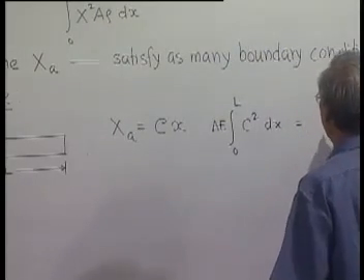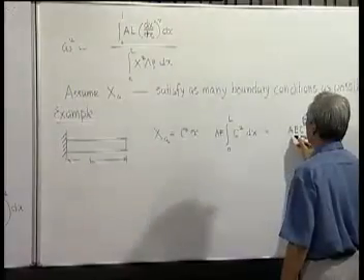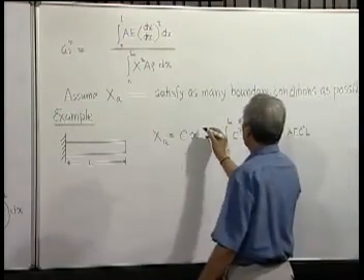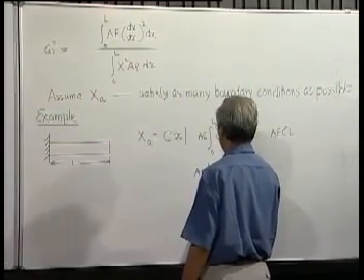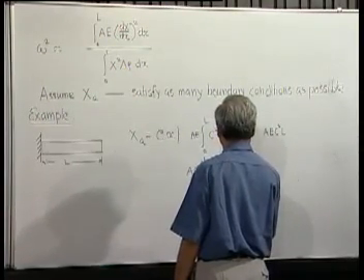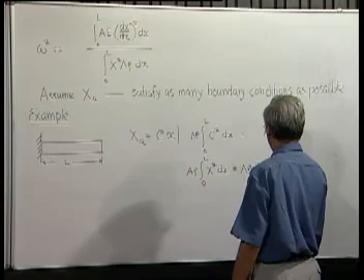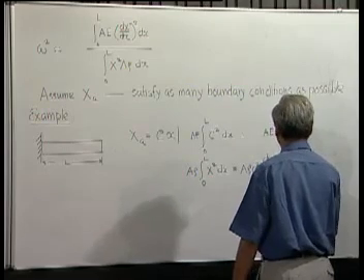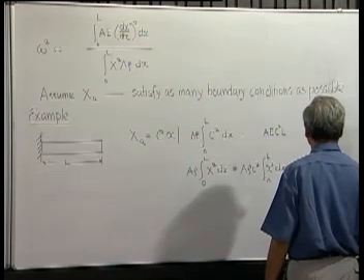So the numerator becomes A E c square L. For the denominator, again A and rho both are uniform as a special case, so this is equal to A rho c square, and it is A rho c square L cube by 3.